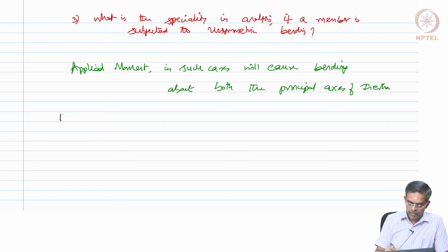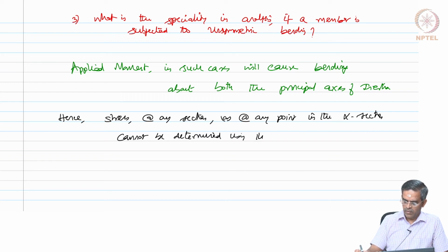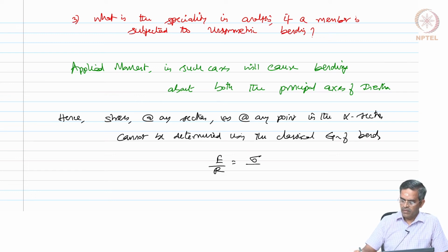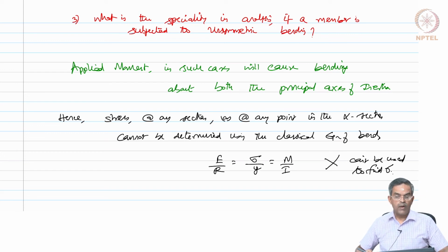Therefore, stress at any section or at any point in the cross section cannot be determined using the classical theory of bending, that is E by R is stress by Y is M by I. This equation cannot be used to determine the stress. Okay. So, it is very complicated problem now.